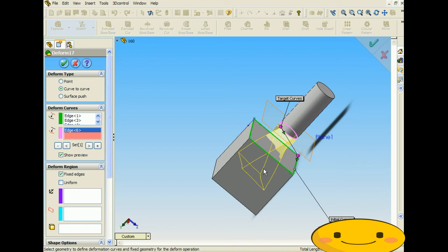And the whole idea behind doing a deform is that regardless of what the sketch looks like initially, you're able to deform the curve to something you would not be able to do normally. If you were just trying to use sketches, it would either take you too long or be something you probably wouldn't be able to accomplish. So this lets you get out of the box, lets you bring an object in the right size, and then lets you deform it, and it doesn't have to rely on the sketch that you had before.